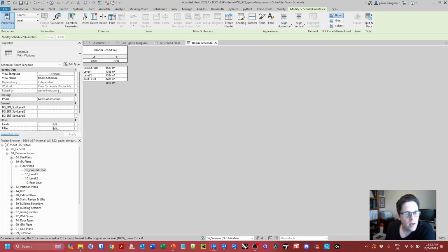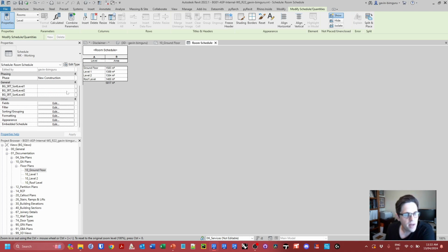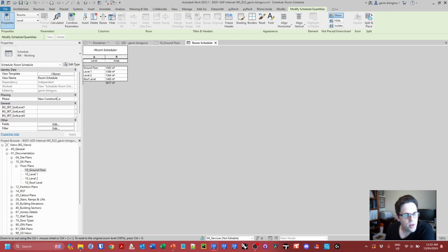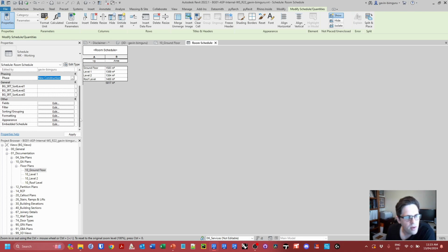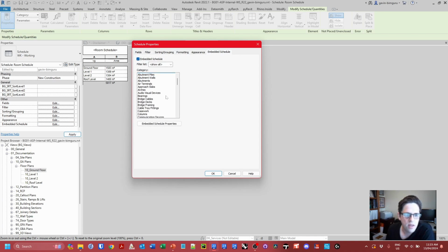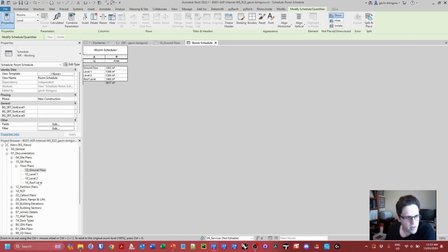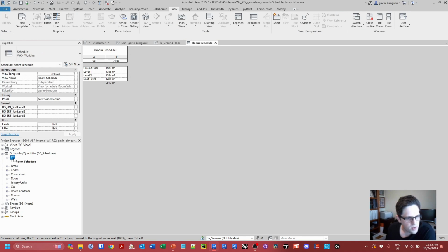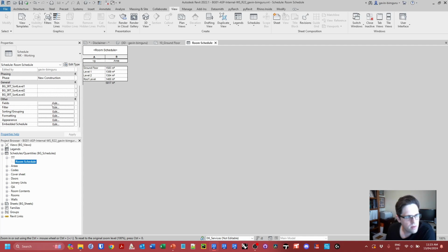In schedules, people don't usually know this, but you can go to the, I think it's the VG settings. Now I'm in a room schedule, so I can change my phase. That's definitely one thing I can do. As well as this, you can embed schedules. We're probably not going to go into this, but I can embed door schedules and things like that in here to report doors in rooms as well. Rooms are a special type of category that support this. I'm probably not going to get too deep into it, but I think you can change the visibility graphics of the view as well.